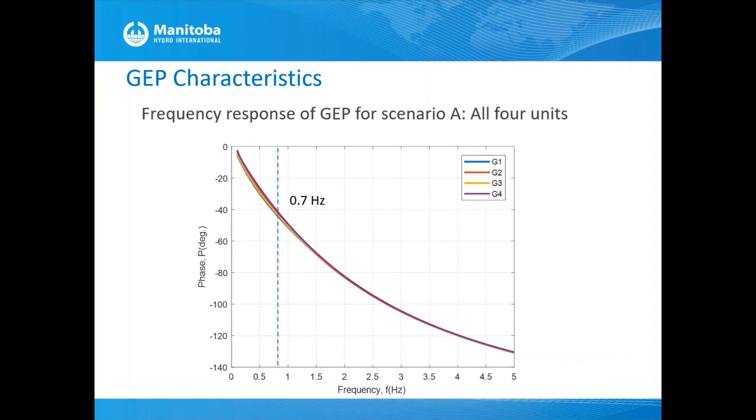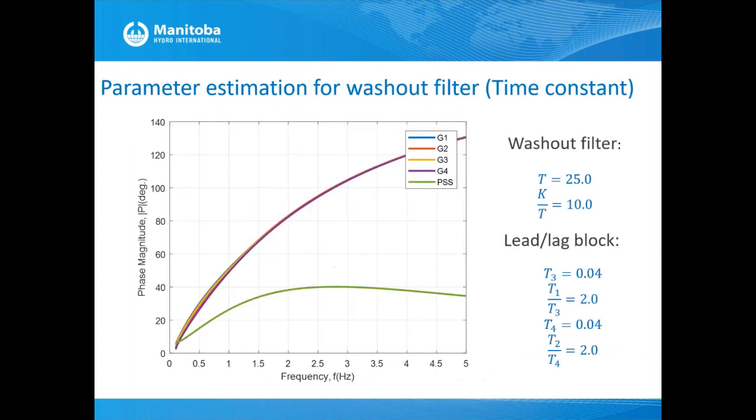Poor tuning of power system stabilizers can cause other problems, such as torsional oscillations having poor damping, because you installed a power system stabilizer to mitigate electromechanical oscillations. So that's why we analyze, even though we did it for 0.7 hertz, somewhere here, we analyze the whole range.